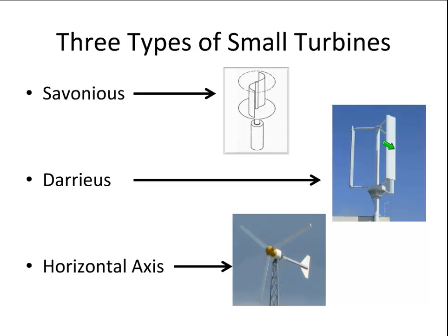When you have lift forces, the tip speed ratio can be much higher. Your tip speed ratio can be 3, 4, even 6, 7 to 1, where it can spin much faster. So if you think about this, the tip of this, as it spins at a couple hundred RPMs at times, it's spinning at maybe 100, 120 miles an hour, while the wind hitting it might only be 20 to 30 miles an hour.